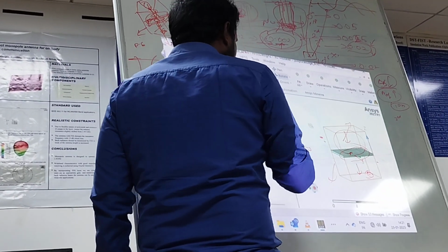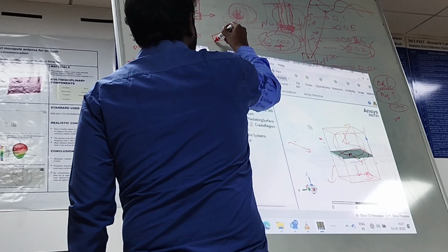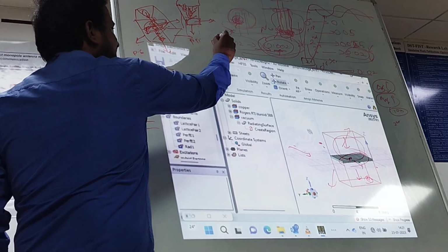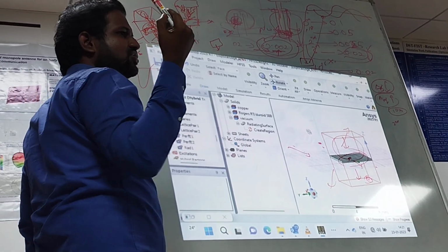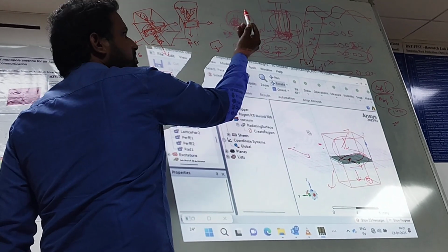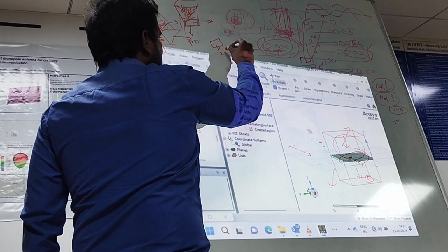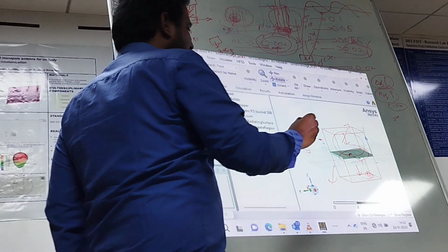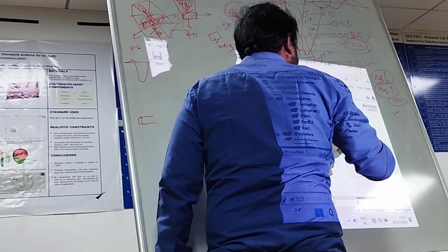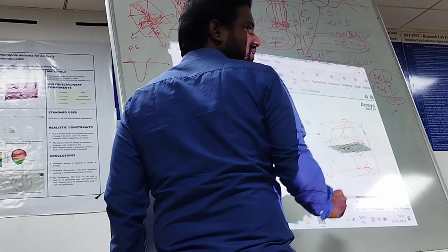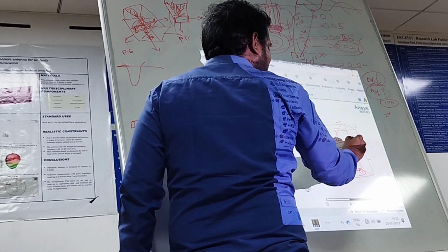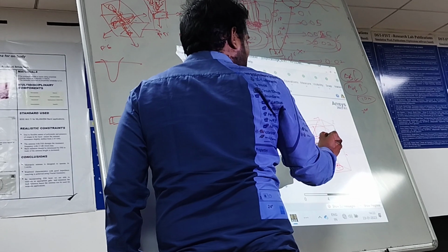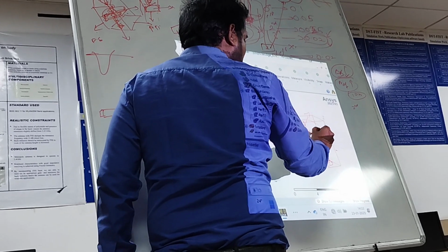So what we will do here is select a particular structure and make that unit cell. We will say this is creating a stop band at 2.4, or let's suppose a pass band at 2.4 gigahertz. Then we will make an array of metasurface over this, like a superstrate. The radiated field that is coming will excite the metamaterial structure or the metasurfaces we had made.